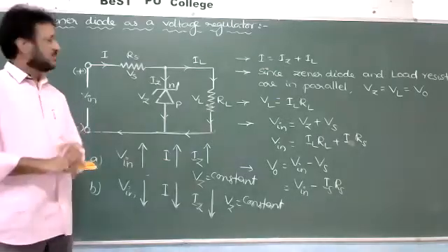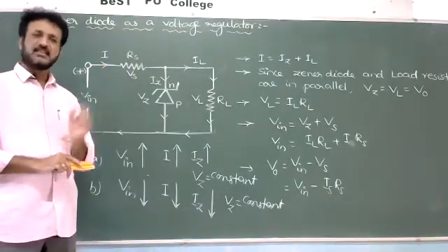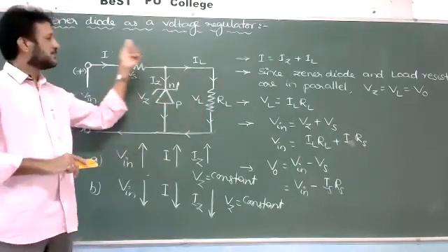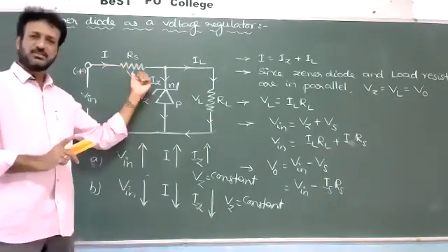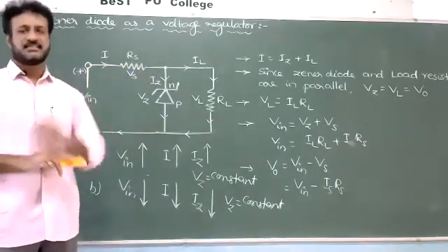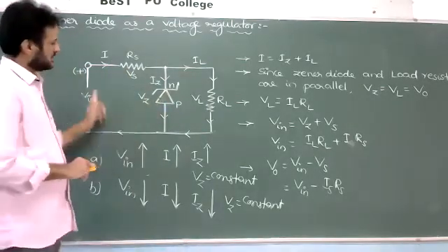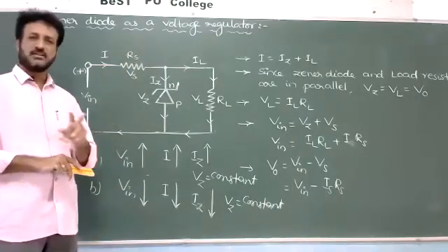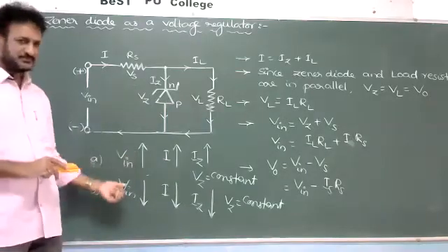That's important. So the value of the RS should be selected in such a way that even in the absence of the load resistance, maximum safe current must be passing through the series resistance. That is a very important point. You have to select carefully. Correct? That is only about the Zener diode, how it can be used as a voltage controller or a voltage stabilizer. So these last 2 paragraphs once again.